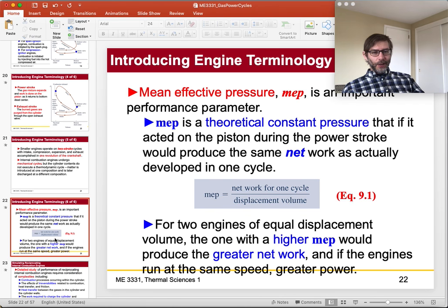But if it's operating at 400 kPa, 4 bar, then it's really not operating at a very high load. So all I'm saying is that this is a useful metric for understanding the scale of the engine, and understanding the power is normalized to the size.